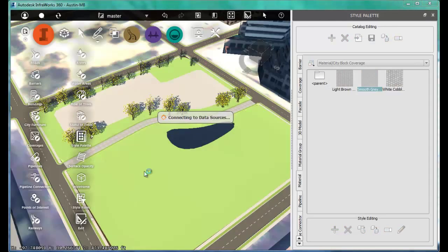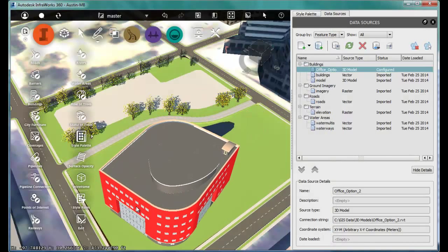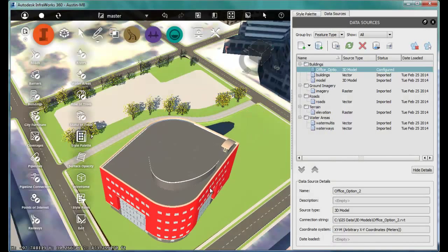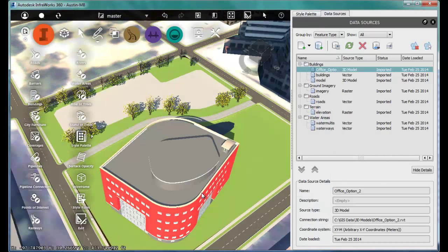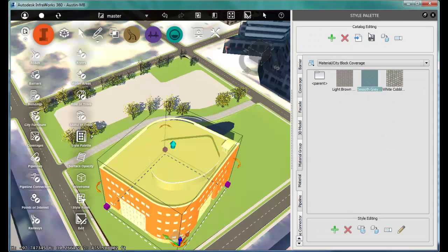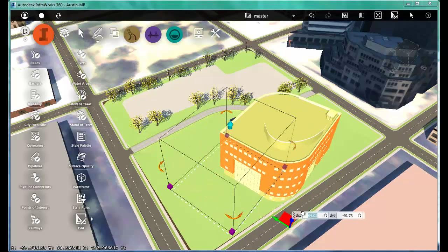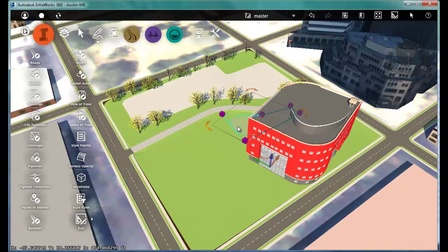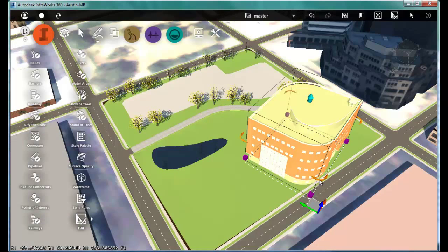With a concept agreed to, maybe you'll want to refine the model again. And with Autodesk InfraWorks, we can consume all that other data you've been preparing, maybe a civil site design, or in this case, a Revit model of the building we're going to put on the site. I simply drag and drop the RVT file directly into InfraWorks. Then I can place the building on the site and rotate or translate it into the position that we've talked about.